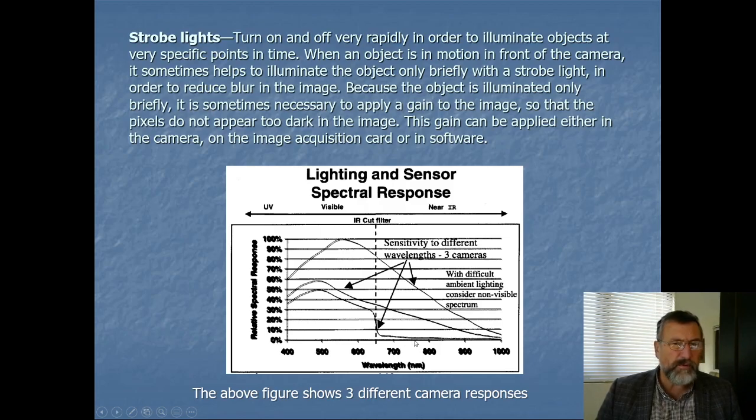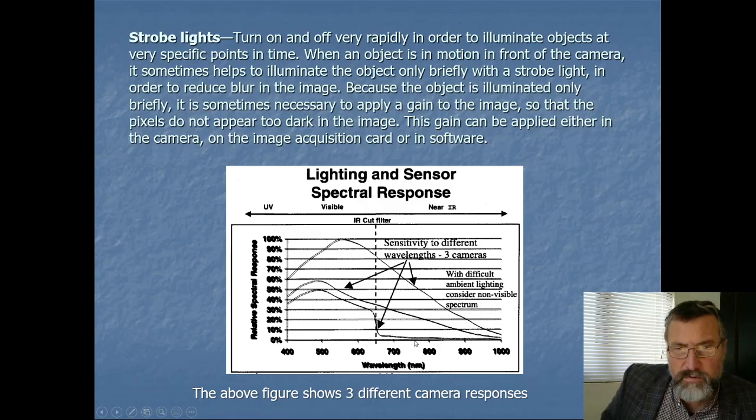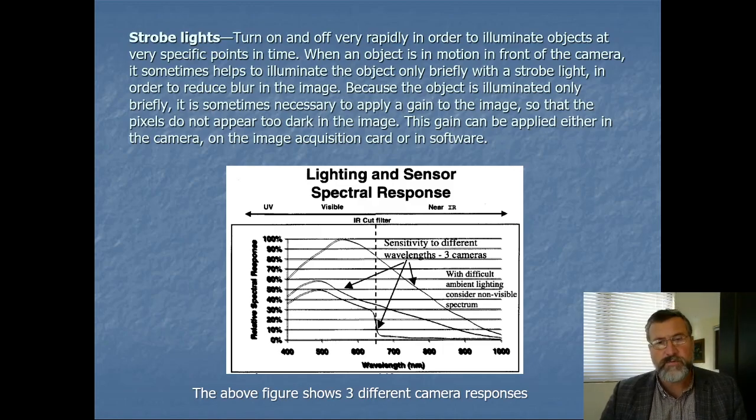Now, this can sometimes be a problem because, one time we were doing a project for a company in the States. We were using laser triangulation to measure objects that were going to be air freight on aircraft. And we were using deep red, so we were using wavelengths about here. But the cameras we were using had this nuisance thing built into them called an IR cutoff filter. These were Sony cameras, but they felt obliged to put this IR cut in. So this is an infrared cutoff filter. The idea of it is, it simulates the way the human eye works by cutting out wavelengths you can't see, because humans obviously can't see infrared.